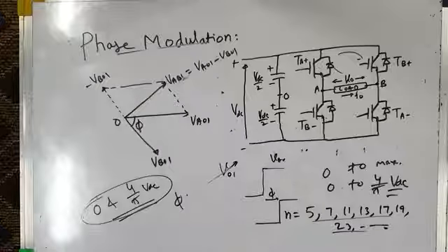For a low switching frequency PWM, we generally go for the selective harmonic elimination technique, or what we call the offline optimized PWM technique, where we can control the fundamental component of inverter output voltage and simultaneously suppress certain selective harmonics, for minimization of weighted THD, or for minimization of pulsating torque, or for some other purpose.